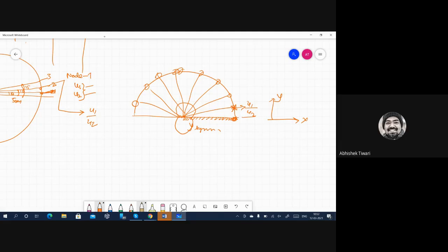What you can do is find the node by coordinates, and you know where exactly these nodes have to be, because if you know that this is 5 degrees, you know where exactly this point will be, so you know the coordinate of that point. Other than that, after meshing, you can see what node numbering Abaqus has done, and Abaqus always follows a rule on the boundary.